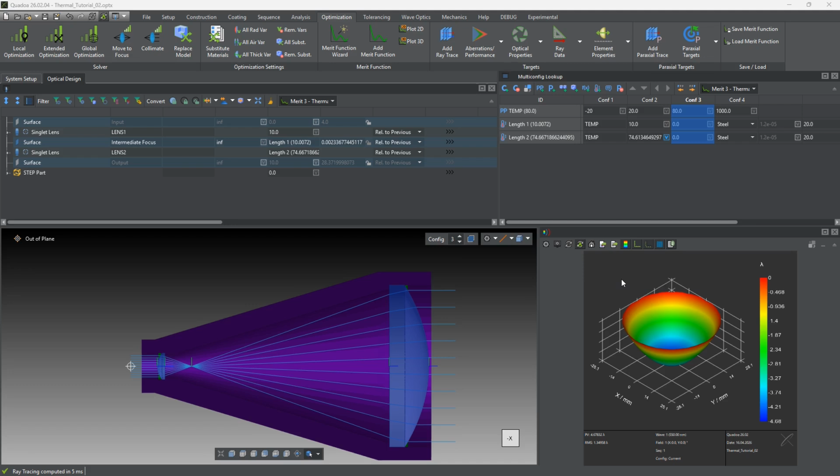And with this design, the system shows a maximum defocus, as mentioned, of about 1.3 lambda, while taking all important thermal effects into account. So expansion of the aspheres, changes in the refractive index due to the temperature change, and the mechanical expansion of our mounting. So in other words, all key influences are included here in our thermal analysis, resulting in a complete first order thermal analysis.